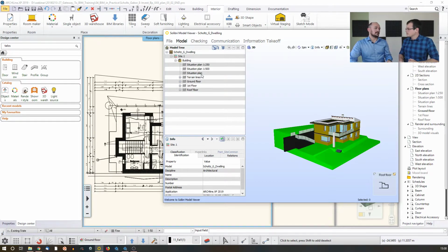And in practice, it usually happens like you pass on the building, and in several other formats, you pass on the drawing itself. If there is a highly detailed final version of the 2D details and anything else, then you can use both. But if you would like to export the building and make the other person able to edit the walls as walls and the columns as columns, you will use the IFC file.